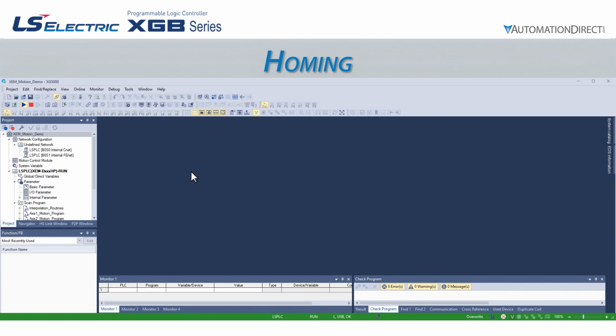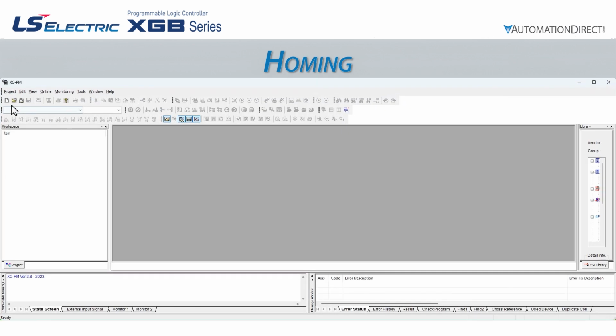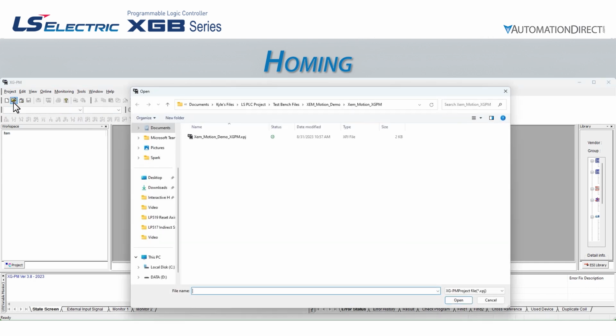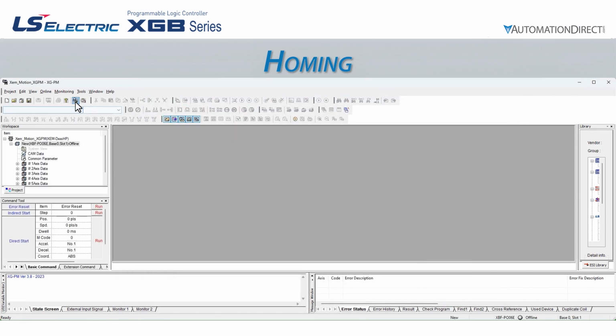Before we start working with the home function blocks in the XG5000 software, we need to configure the access properties in XGPM to execute the home functions that we want. Let's open XGPM from the XG5000 programming interface by going to Tools, Position Control. We can then open the XEM Motion Demo XGPM file. We will connect with the controller in XGPM as well.